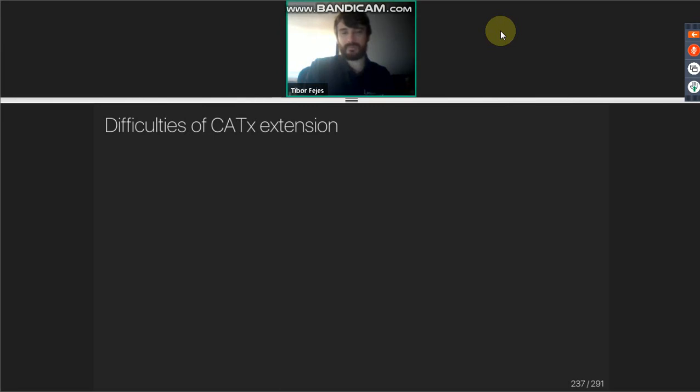So as I mentioned earlier, there's aspects of Cat-X cables that mean they aren't particularly suitable for sending the raw HDMI signal. They're much thinner, so they're more vulnerable to attenuation. And as I mentioned in an earlier session, attenuation increases at the higher data rates and frequencies. So it increases exponentially, and HDMI is using much higher frequencies than what Cat-X cables were designed for.